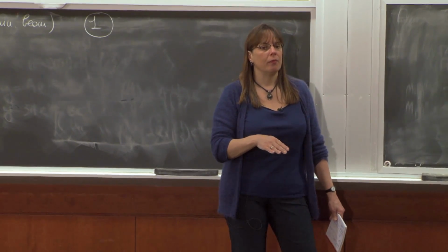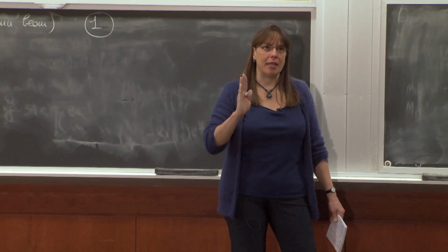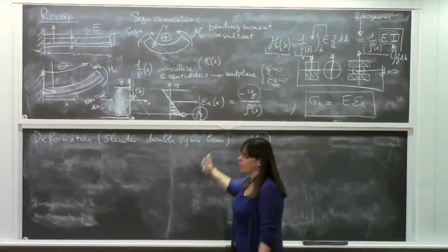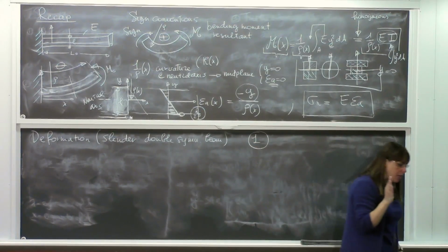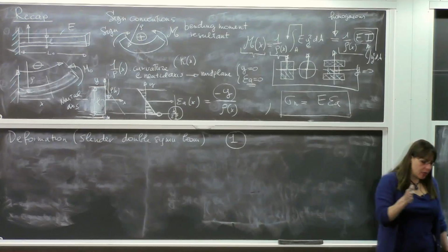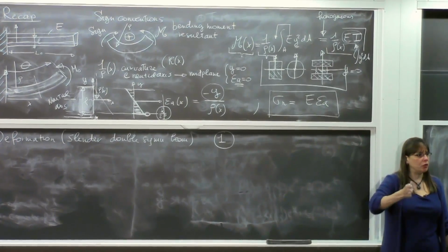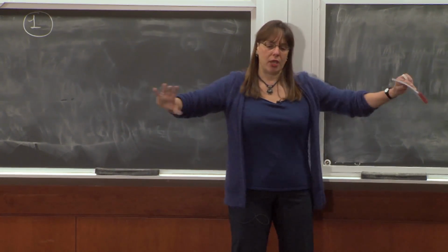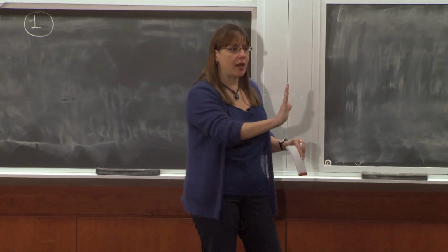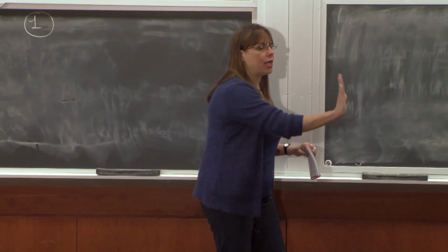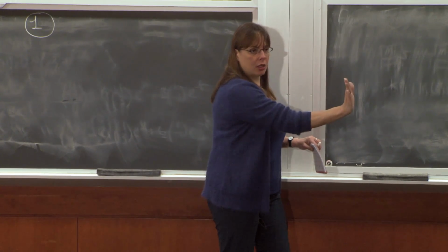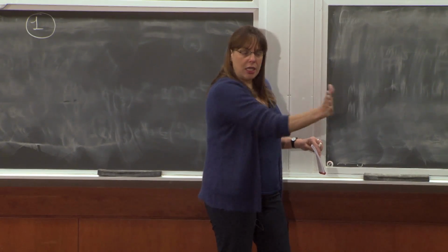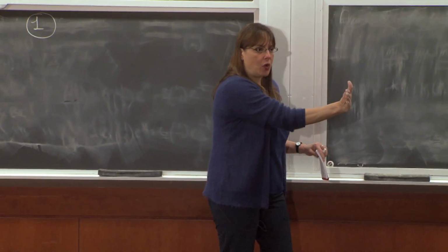The bending, that's curvature. That's the bending, yes. But the question that I have is, I need somehow to connect curvature and strain. And remember, when we started in axial loading, the first thing that we said was that all the section moved together and has the same u deformation. And when we did torsion, and we had a long shaft, the thing that allows us to derive the relationship is that on the section at x, the whole section rotated by phi of x. It all rotated together. In axial loading, the whole section moved in u of x together.